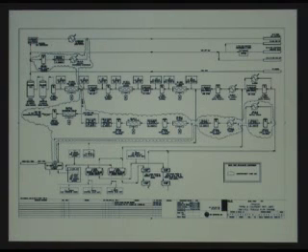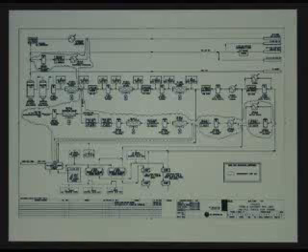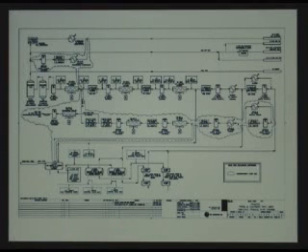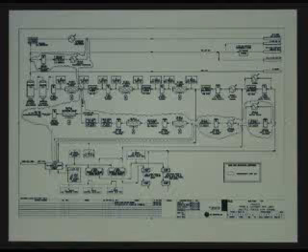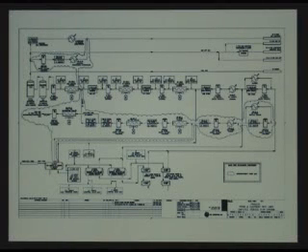So how do you start this train up, and how do you then shut this train down so you can swap load between the two without overpressuring the cooler or potentially underpressurizing, or what's worse, start pulling slugs of fluid out of the separators? That becomes an interesting point of consideration when you start thinking about how the equipment's going to operate.